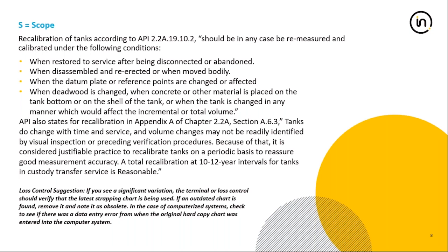Also, whenever you do something that changes or affects the datum plate, which is the plate at the very bottom of the tank where you rest your gauging tape, or you change the reference point at the very top of the tank from where your tape is going to descend into the tank, the distance between those points related to each other is going to affect the measured volume within the tank.